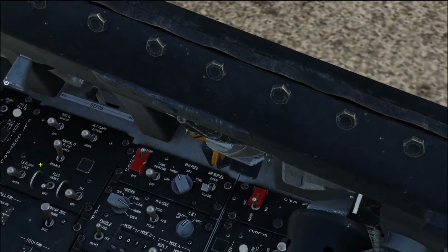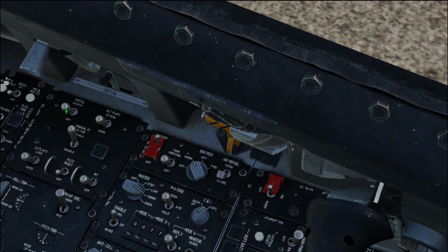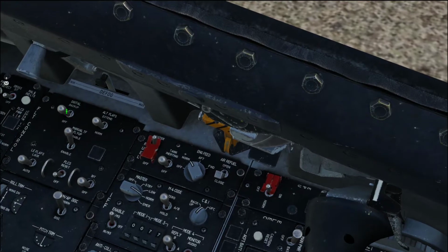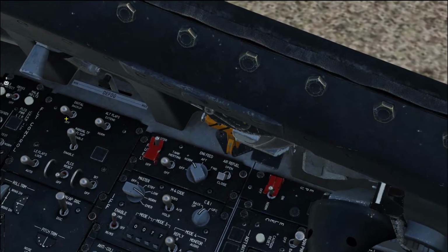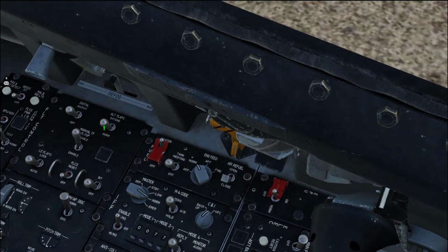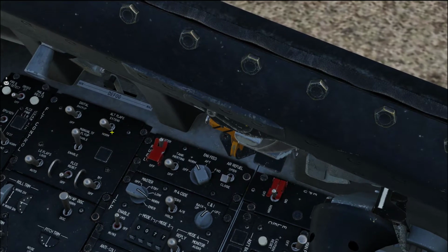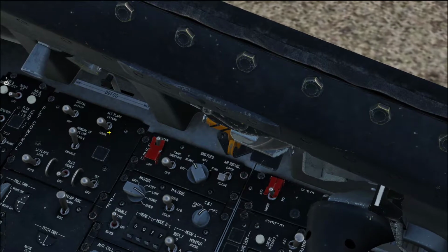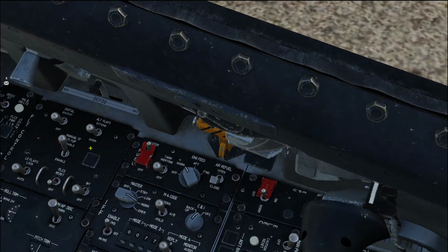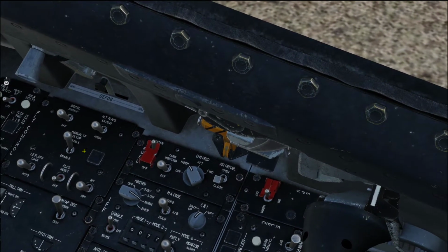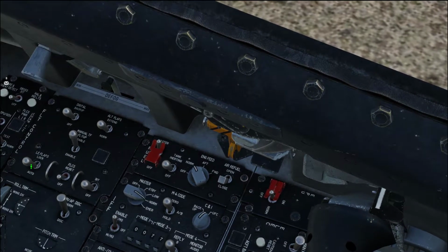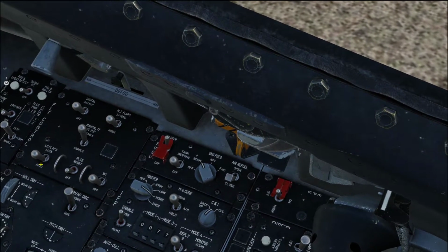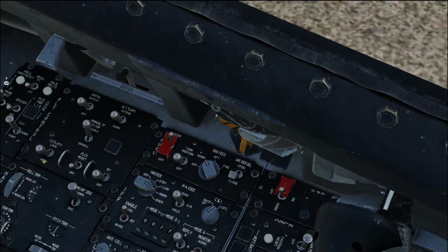The first switch on the left is to turn on and off the backup mode of the flight control system. The next switch is used to extend the trailing edge flaps or normal position for their automatic sequence. The bottommost row towards the left side, we have the leading edge flaps to the lock position and for their auto operation as per the flight control system logic.